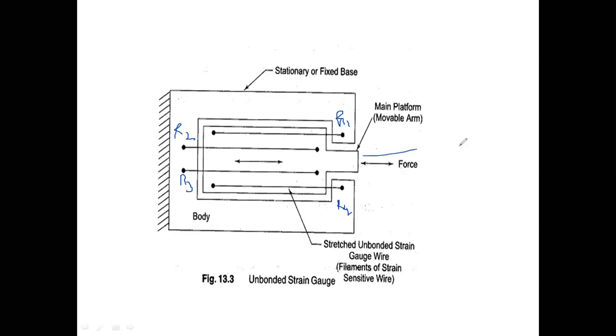If I apply force like this, what will happen? R2, R3 will be stretched. They will elongate. R1, R4 will compress.